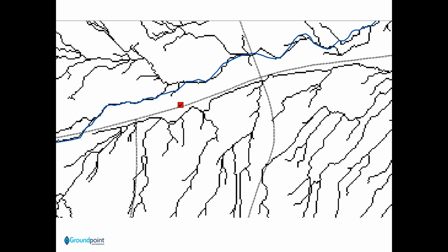We also need to look at the GPS data critically, and here's a kind of a classic GPS problem, right? Where's the culvert? We can model any point on the surface model, but the points need to be located properly. So we have to look at where exactly this culvert is in the real world. Is it any one of these 4 points?